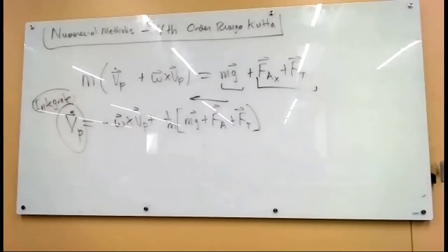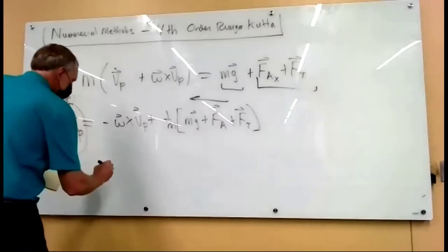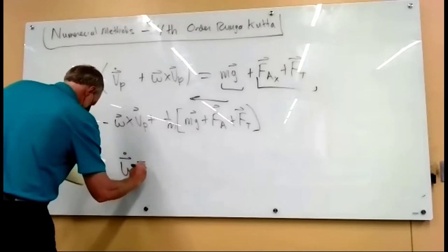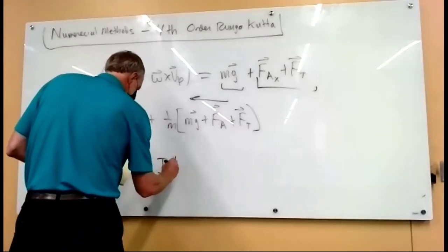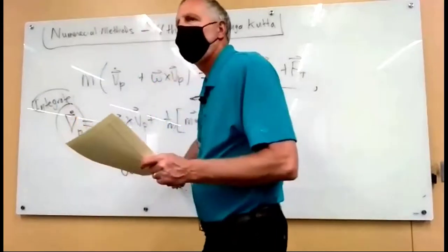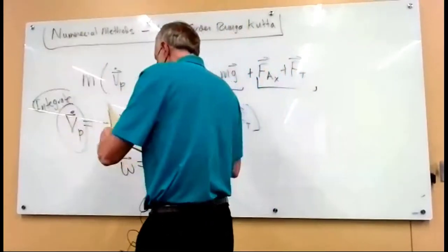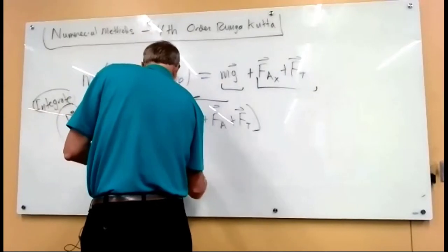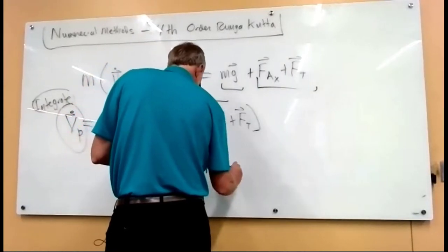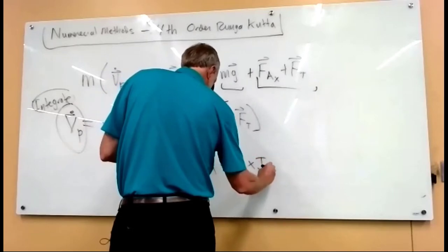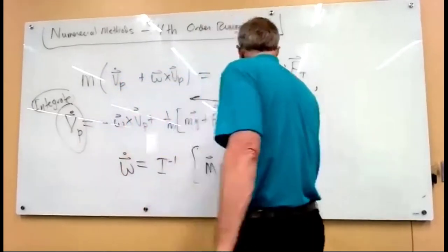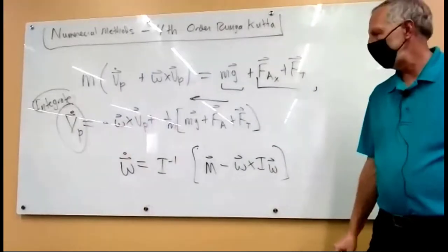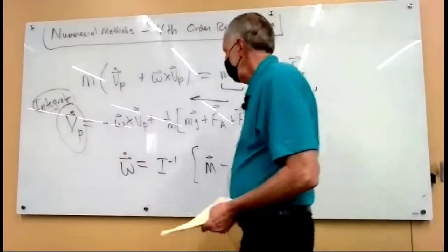All right, and then we have the moment equations. There's three equations for P dot, Q dot, and R dot, the ones that we looked at here. That's the roll, pitch, and yaw equations. And if you write those in vector form, after we've already figured out what the inertia terms are, the IXX, IYY, you rearrange those equations. There's the applied moments. Here's the omega cross I omega that you can write all of those cross product terms in. And then MATLAB integrates this thing.